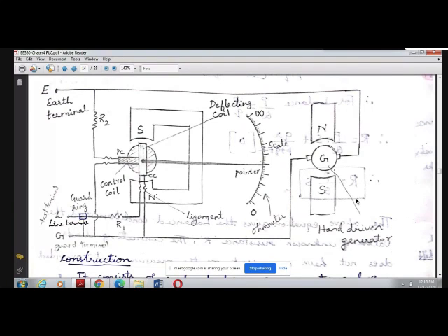Then what happens, as the circuit is kept open circuited, you can see on the ohm meter that it is marked as infinity and 0, and there are all the other readings. One side infinity is mentioned, and on the other side 0 is mentioned. So when you keep the megger open circuit, without connecting anything across these terminals, if you rotate the generator handle, what you should get is infinity.